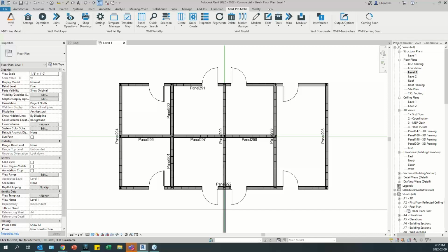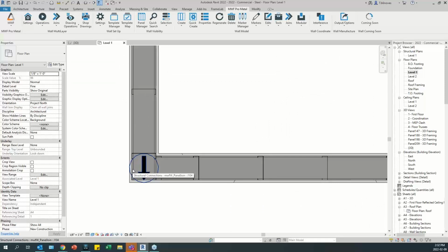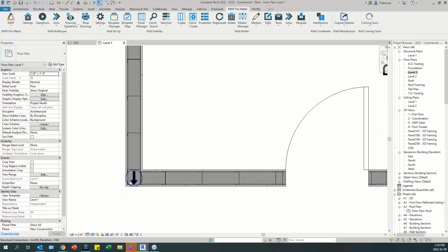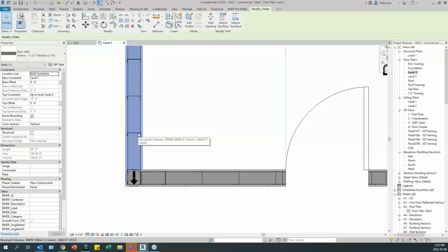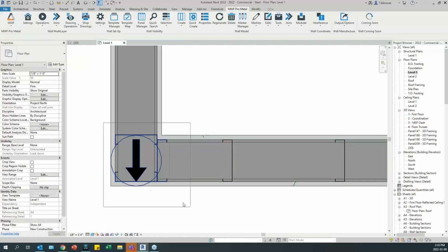But the question is, corner markers, is there a way to have all the studs be the same family type? Okay, so they are only going to be the same family type if you set this up in the template. For example, if you have one template with 8 inch studs, and in the other wall you have a template with 6 inch studs, there's no way for you to control and say that all of these members from the corner will be just one family.